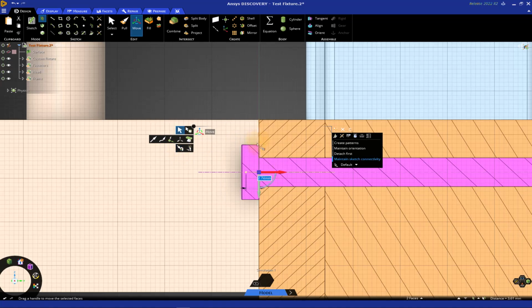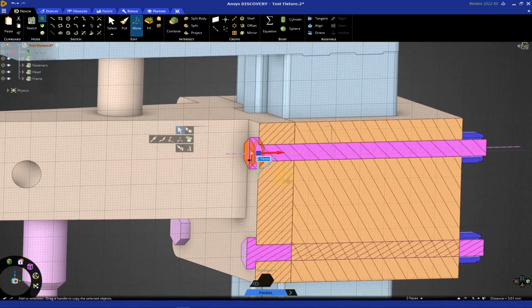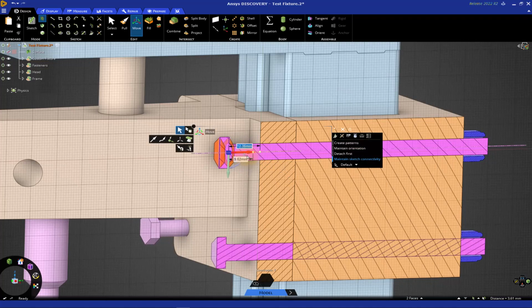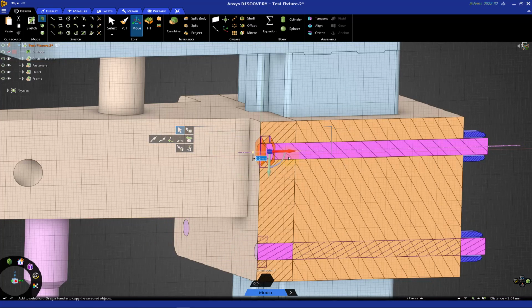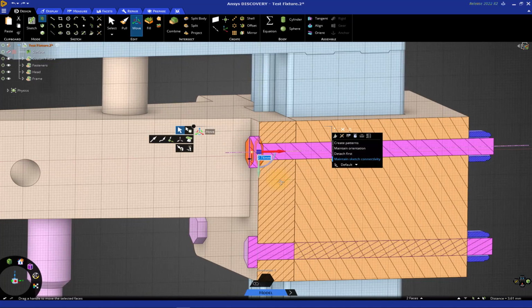Now I want to zoom out and show you that if I were to edit this bolt now, you'll notice that the other bolts are updating. Now, it just so happened that the other bolts also had a space, and by editing one, the other ones updated because they are instances. When we want to move all of the instances, we select either faces or the solid.